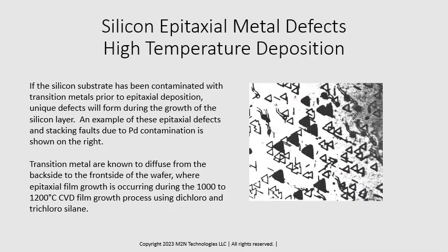On a project I worked on, we looked at using silicides in single crystal silicon structures using epitaxy. We found that if there were silicides on the starting wafer or even embedded in the starting wafer, they would diffuse through the wafer and form precipitates on the surface, which would cause epitaxial defects.